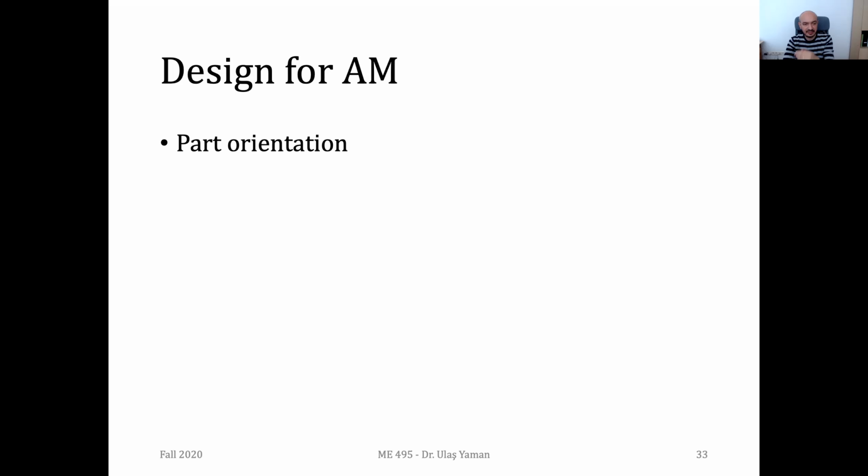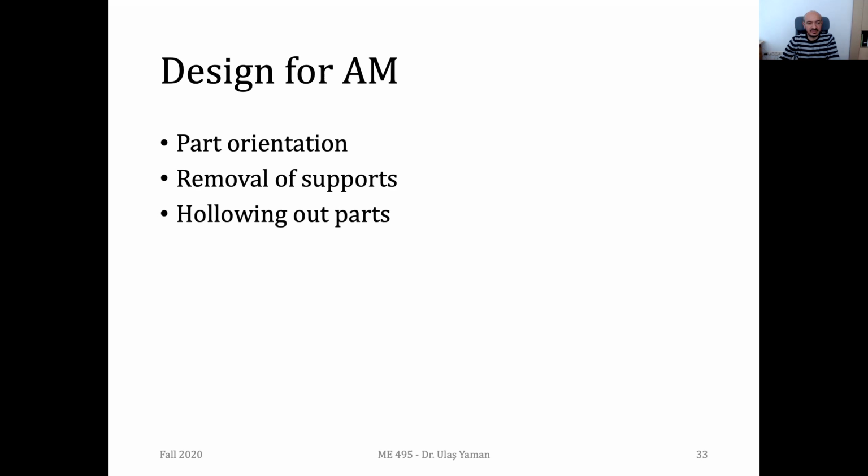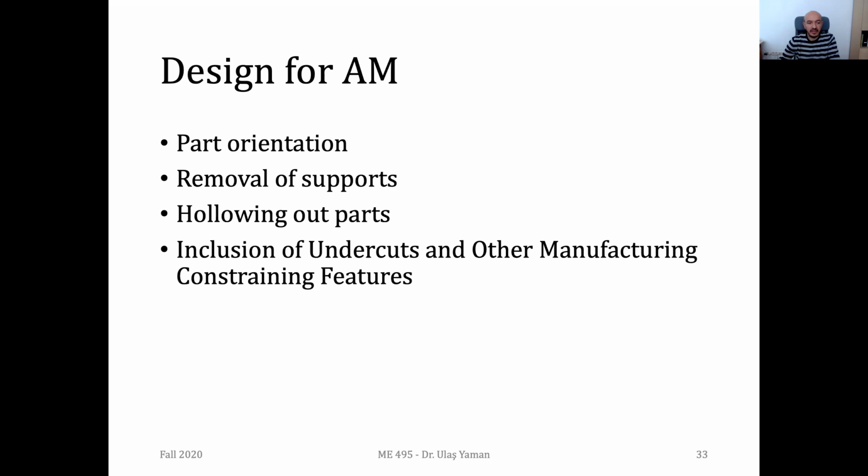So the orientation and some angles on your design are quite important, since you'll need to spend time on the support removal. We will spend more material for the support structures. Another issue,